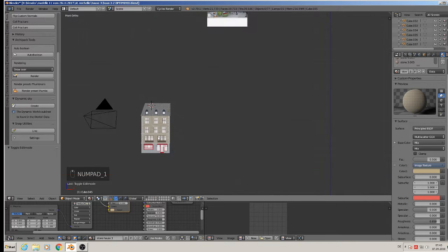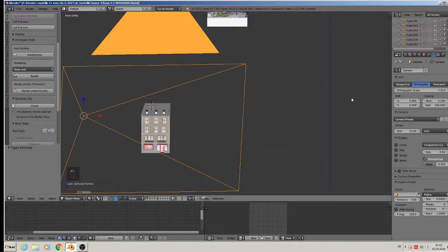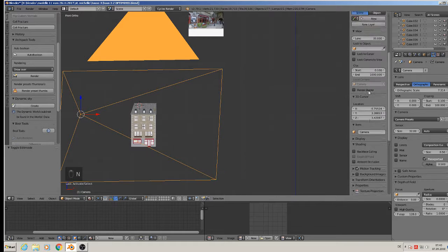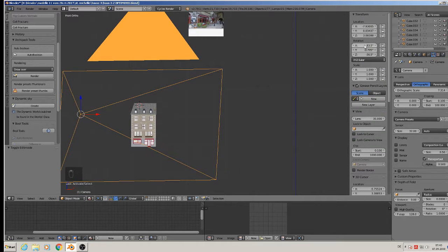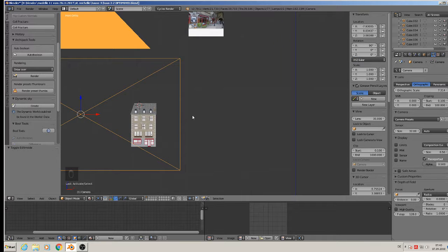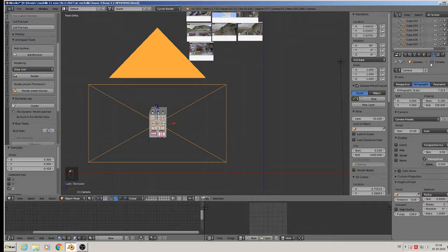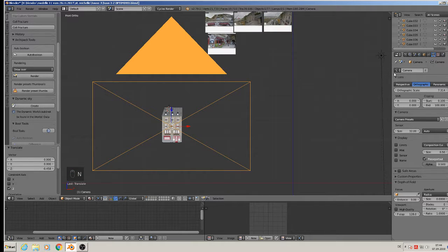We now want to make the photos from our house there. So we need the camera on orthographic view. N to open that panel here. And X should be 90. The rest 0. Then you have a straight look from front. Good. We hide the panel again.